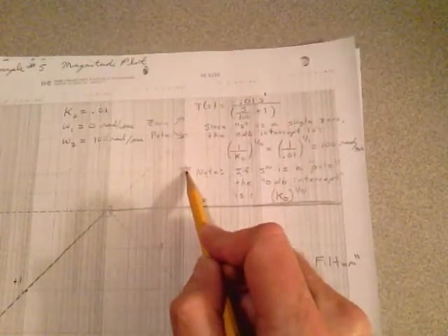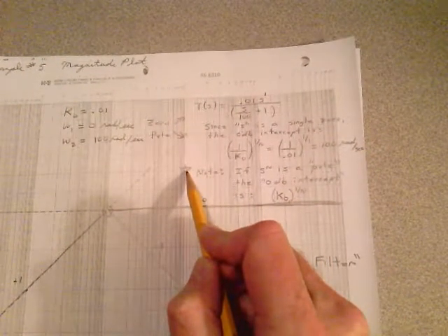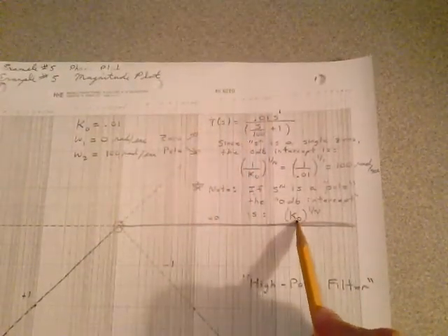I will give you a note here that's really important. This is on page 112, and it says that if the S to the N term is a pole in the denominator, and it wasn't in this example, it was a single S term in the numerator, that was a 0. But if that single S term, like it's going to be in the next example, is down here in the denominator, you have to use this formula for the 0 dB intercept.